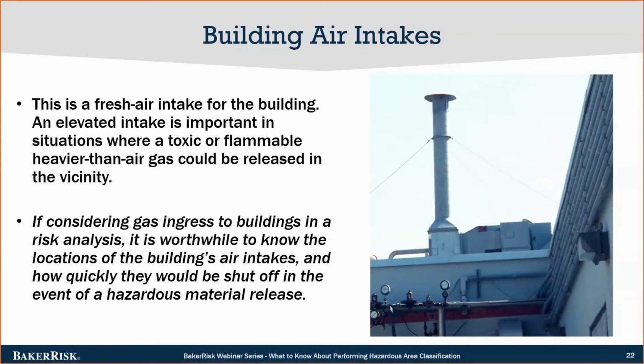So it's very important that you examine the building, what's happening with its ventilation system. Is that ventilation system appropriate for the hazardous area classification and for the desire of normally trying to maintain inside the building that you can use general purpose or unclassified electrical equipment within that building, regardless of what the interior of the building classification would be.